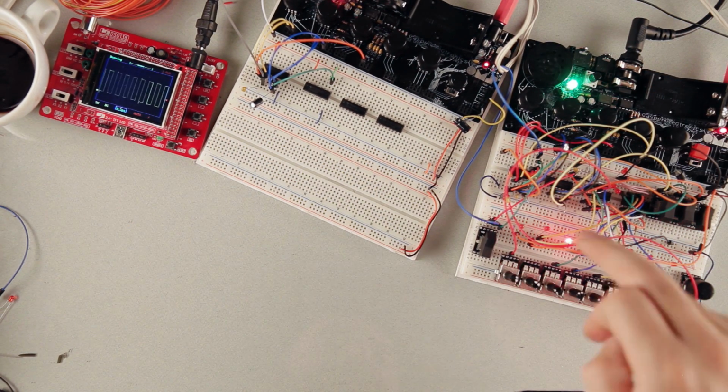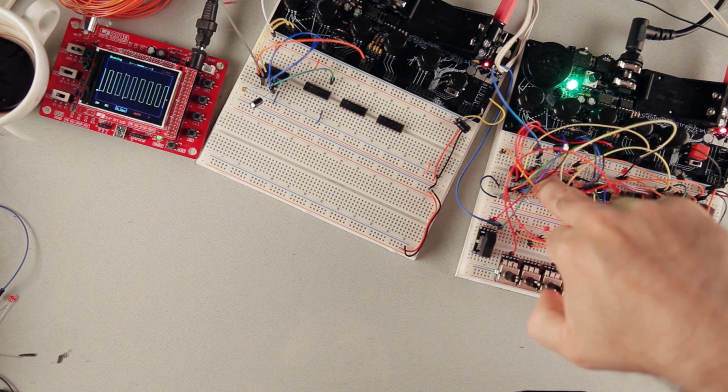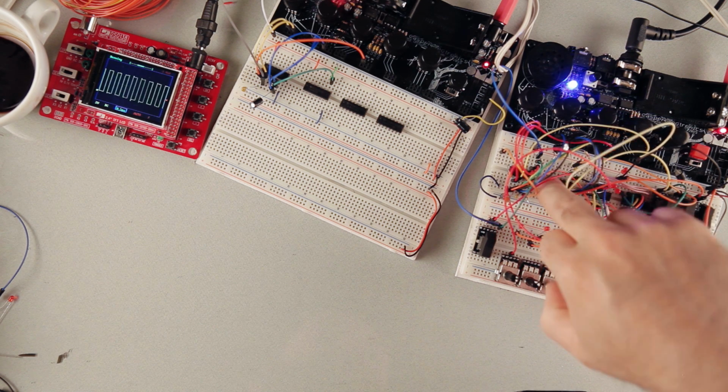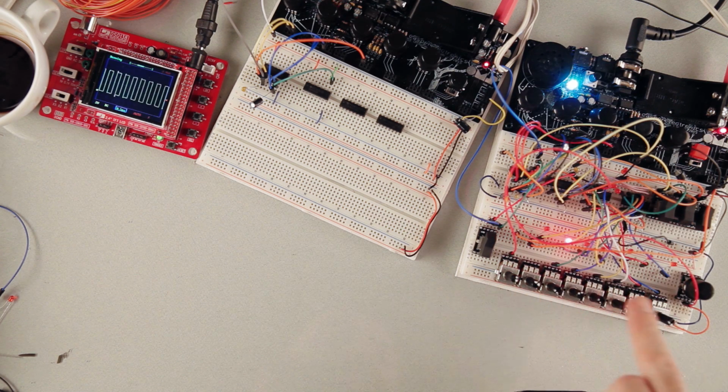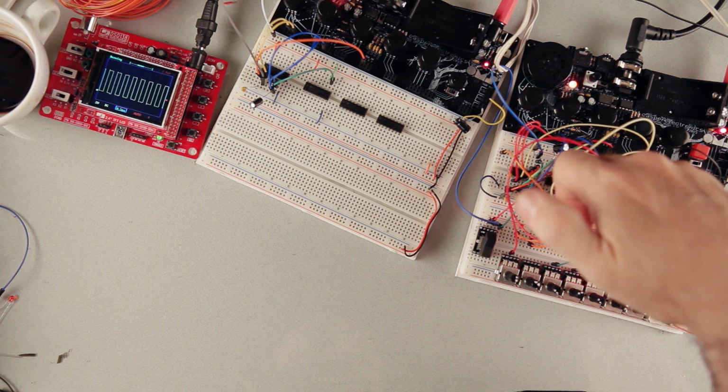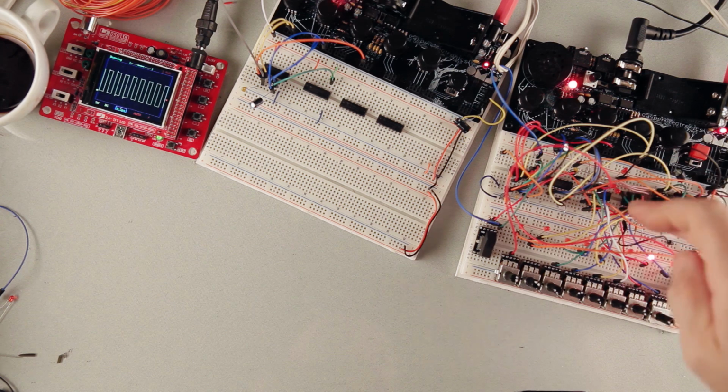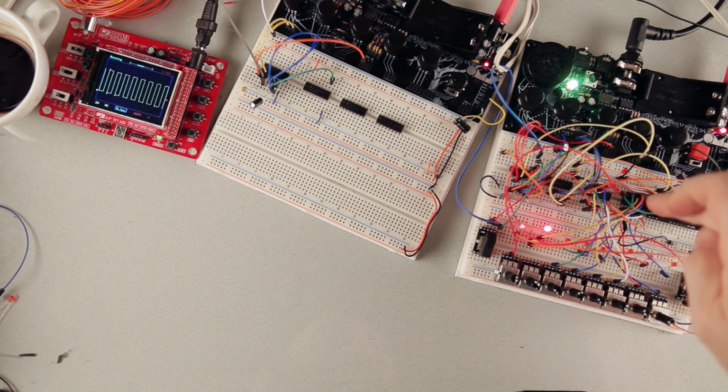Here's just before I start building, just to show you again, this is the circuit. So we've got our oscillators here. We've got our audio and our sub-audio oscillator. The sub-audio is clocking our sequencer. Then we've got our divider here, the 4040. And then we've got 2 multiplexers.